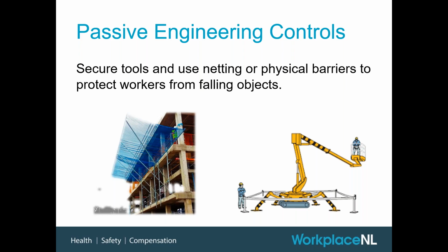And it's not uncommon to see debris netting on very high scaffolds where you have a lot of people working at different levels, and also above our public streets. If you have a walkway, say for example an exterior walkway that has a lot of pedestrian traffic, sometimes they'll build a scaffold above to protect people down below from accidental materials falling or dropping on them.